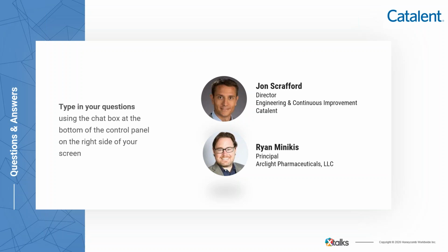So the recommendations earlier regarding using a larger nozzle orifice with low pressure were really intended for amorphous solid dispersion programs going into a solid dosage form, like a tablet or a capsule, where in most cases, larger particles provide improved performance and ease of downstream handling. If your program is targeted at nasal inhalation, then certainly generally smaller particles provide improved performance. And in that case, you would adjust the atomization parameters to make smaller droplets. So as the question stated, that's when you would be looking at using higher pressure in a pressure nozzle to generate those smaller droplets and thus smaller particles.